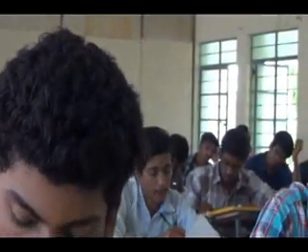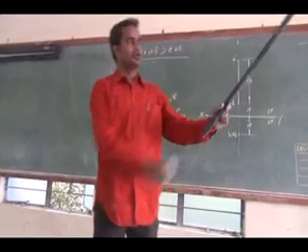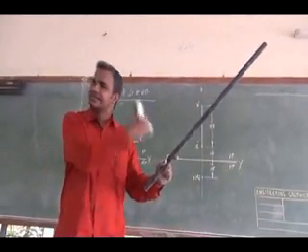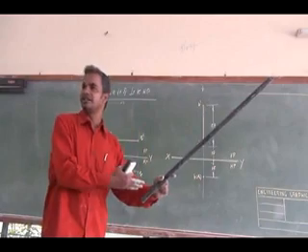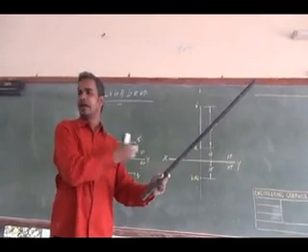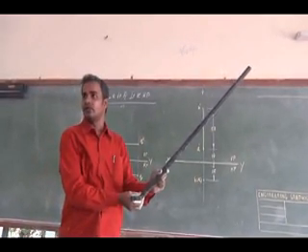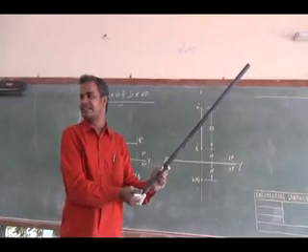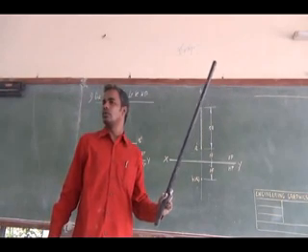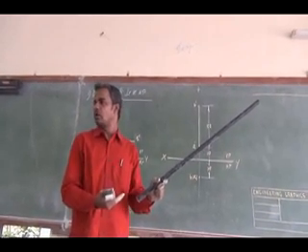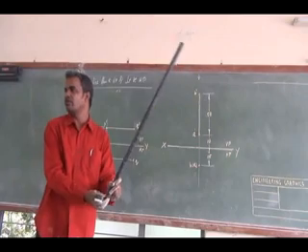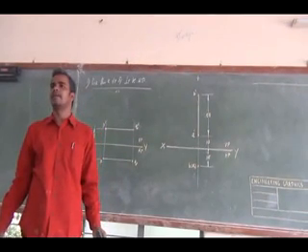Okay, this is the other. See here. So I have a line of length 65 mm and the line is 30 degree inclined to HP and it is parallel to VP. This is how the line orientation is. Right? And one end, the one end in the sense, the nearest end, is 10 mm above and 15 mm in front of. Okay, the 10 mm above and 15 mm in front of is given. Right.